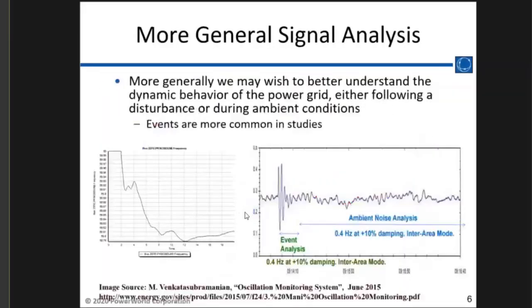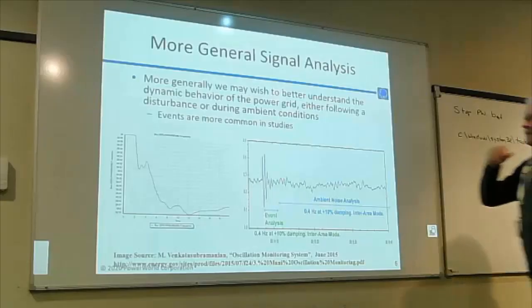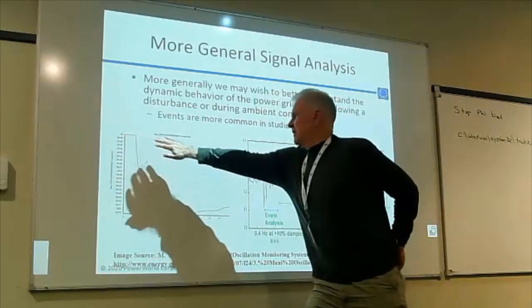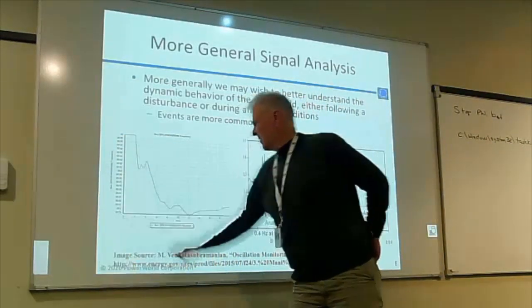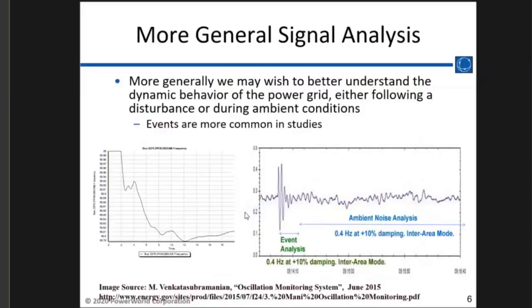Okay, so what's very common in doing a dynamics run, a transient stability run, is to get a frequency, and this is 60 hertz, and this is, I think, like 59.8 hertz, and you get something like that. It's very common to see. Now when I look at that, I think, oh, that's so easy to decompose into its modes.